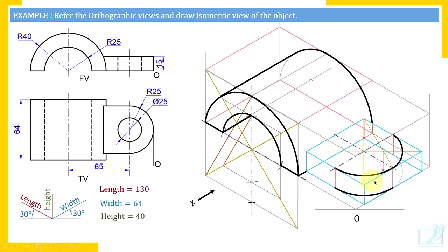Now this surface is a semi-cylindrical curved surface. So you should draw its boundary. This is the boundary of the curved surface. That is the boundary generator. It is called the boundary generator. So here I have drawn the boundary generator, and now only the boundary portion of the smaller arc will be made dark. And now where the U-shaped plate meets the semi-cylindrical surface, how to create that joint, try to understand.